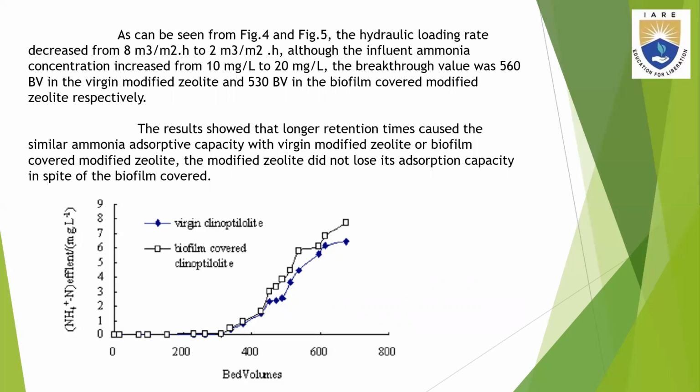The results showed that longer retention times caused a similar ammonia adsorptive capacity with virgin modified zeolite or biofilm covered modified zeolite. The modified zeolite did not lose its adsorption capacity in spite of the biofilm cover.